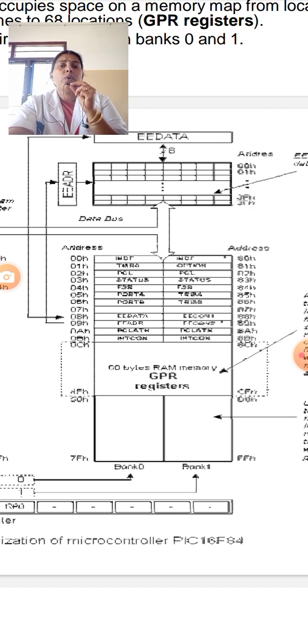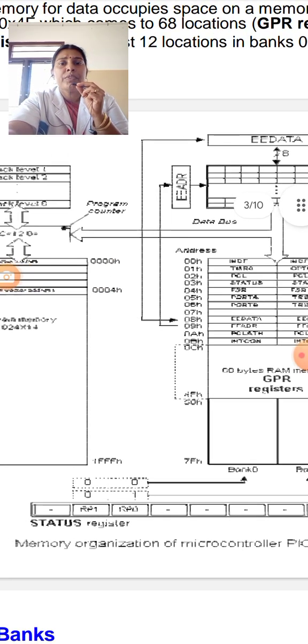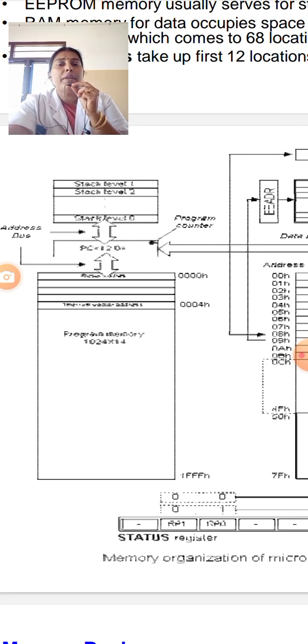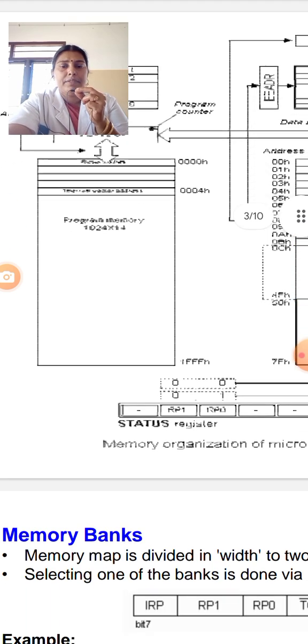The different locations of address for a microcontroller PIC 16F84 is presented as an example. The same scheme will be followed for other microcontrollers also. The number of address bus and data bus may vary depending upon the memory which is being consumed. If it is designed for more memory, more number of address bus and data bus will be allocated.